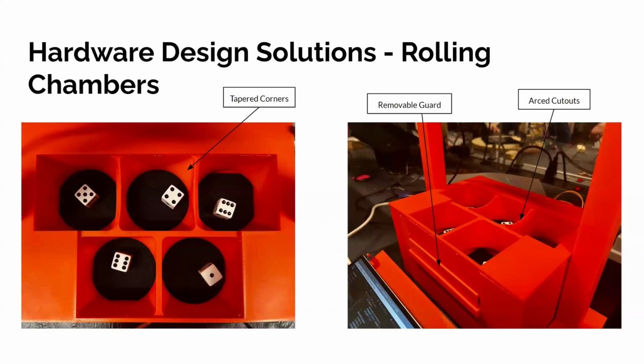The chambers themselves required a significant amount of prototyping in order to produce a reliable and consistent result. The chambers themselves are each 2.5 by 2.5 inches wide and have a small cutout along the edge 1.5 inches from the top. The chambers were arranged in the zipper orientation to condense the image the camera would need to read. The adjustments that needed to be made were the tapered corners of each cell and an arc cut out between the 3 cells in the top row.